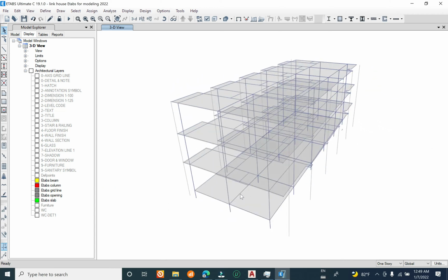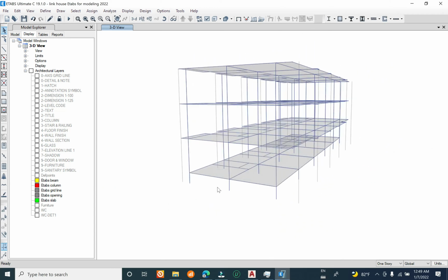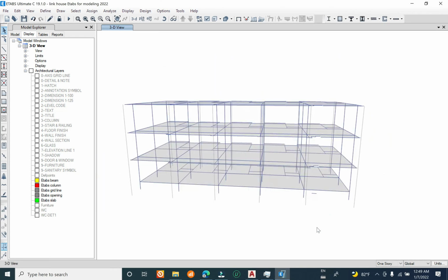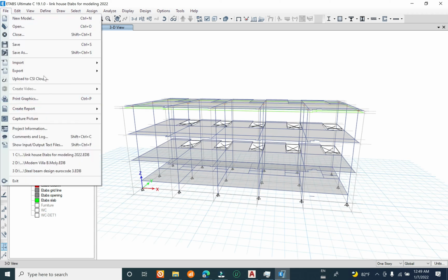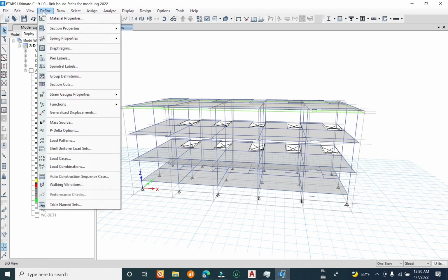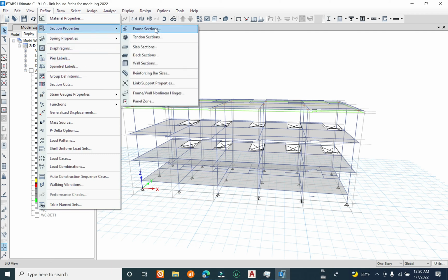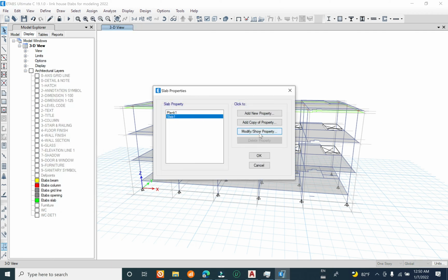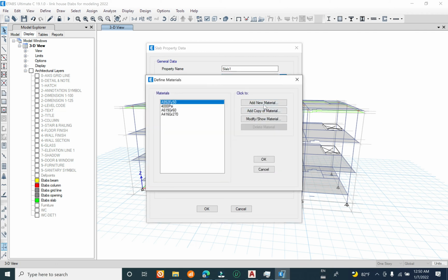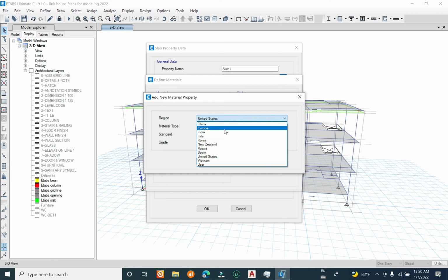You cannot model the complete shape directly in Etabs, but you have to use the DXF file to help you to model the complete shape. Okay, now that everything is fine, no other error. We have to change the slab section from 1 to 120. Okay, we keep everything in the zero code. We have to add a European concrete.